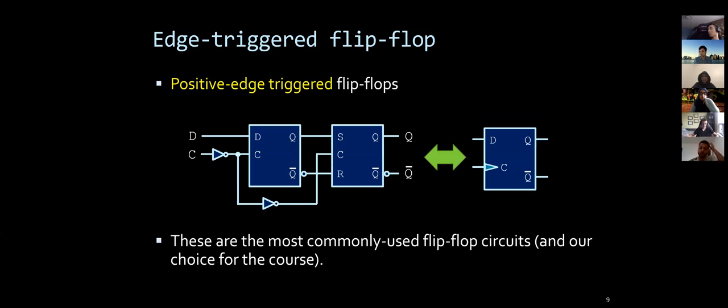So the question is, if we can change S and R when we want to change Q, why do we need a clock? This is why I talked about instability of the results. Remember, the problem is that we don't like the input conditions under which there's some non-determinism, like a race condition. We can deprecate them, but essentially that's still an undesirable situation. So you want the timer to be able to control when things change, right? Otherwise, when I draw all the circuits without timing, remember I was always saying time t plus 1, but how are you going to control it, right?